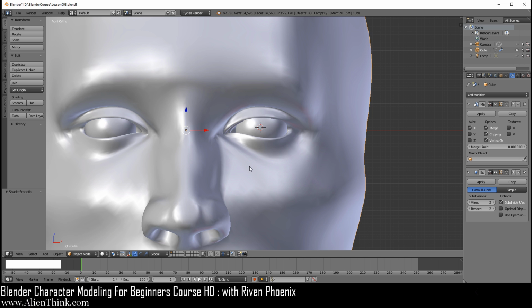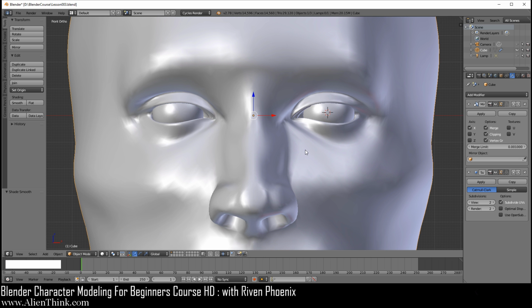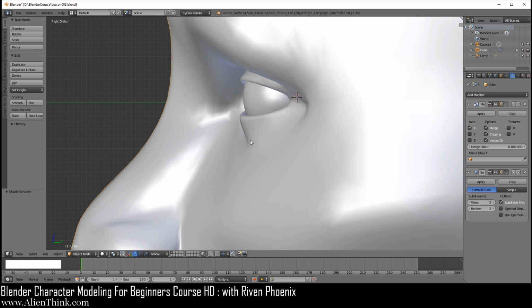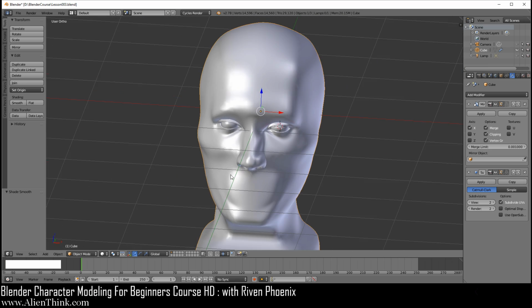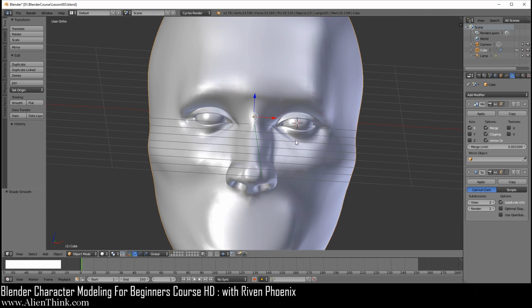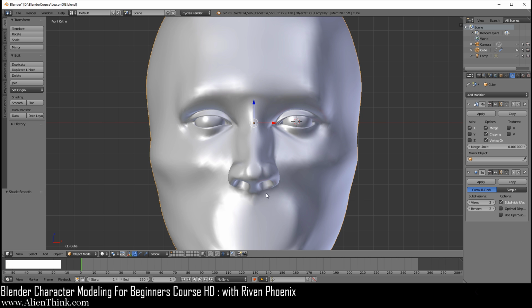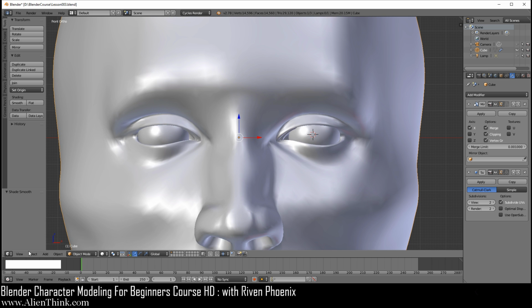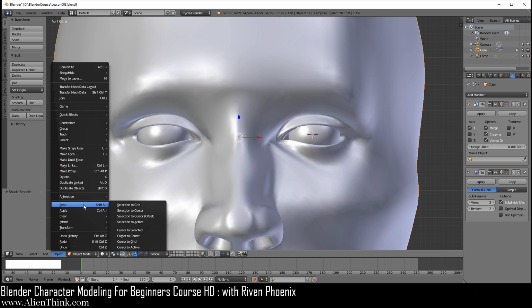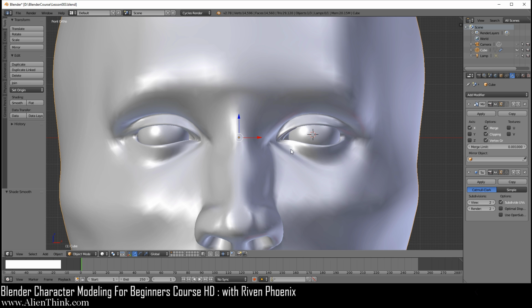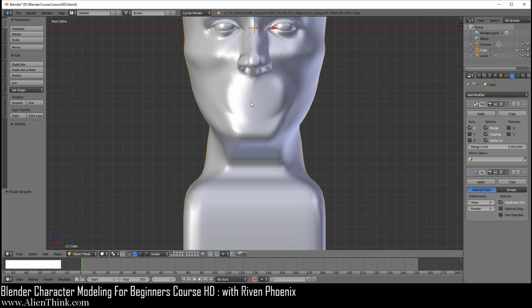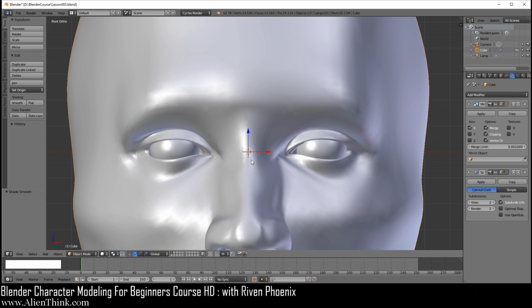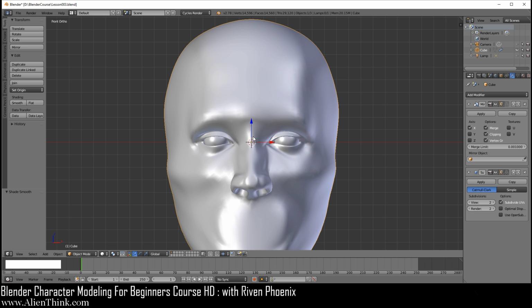Okay, so now what we've done is correctly define the eye. Now you can look at it from the right view over here and just look at it from different angles. Make sure you're happy with the results. So you can see that we were able to quickly define the eye and the nose so far with this formula-based system. So now you can see that the 3D cursor is over here. So you can go under object and do snap. You can do cursor to center, or you can simply do Shift and C, and it will simply move the cursor right smack in the center of the actual grid.